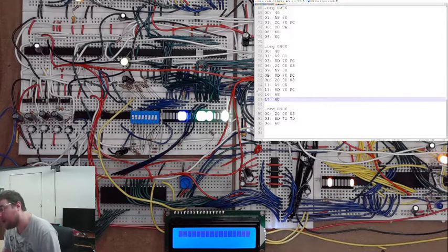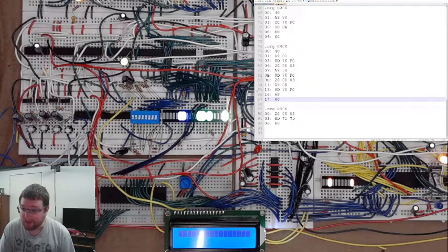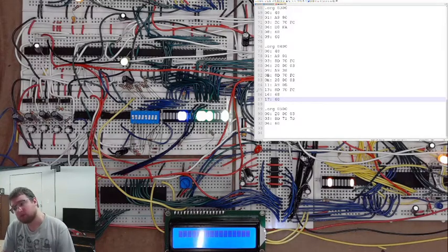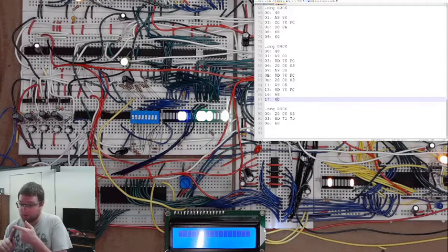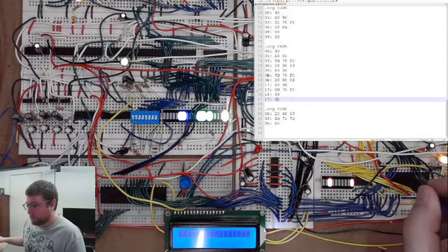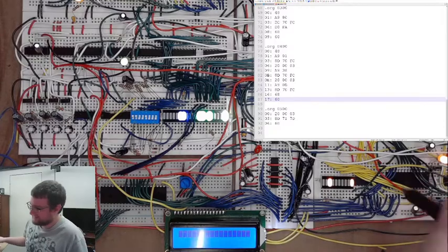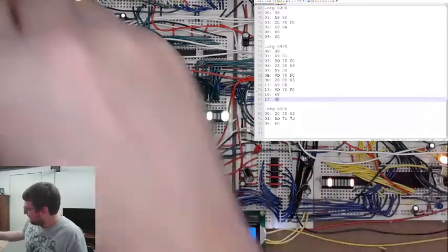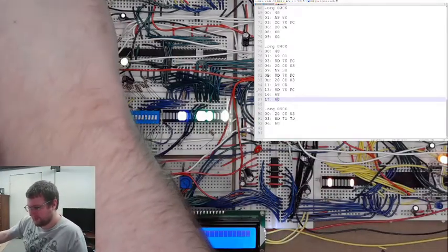So, oh wait, we have 256K of SPI EEPROM. So I'm probably going to use that mostly for like lookup tables later. You know, it could have the boot code in it, but so could, I mean, this has to have boot code in it. But the boot code could just say, okay, boot from SPI EEPROM.